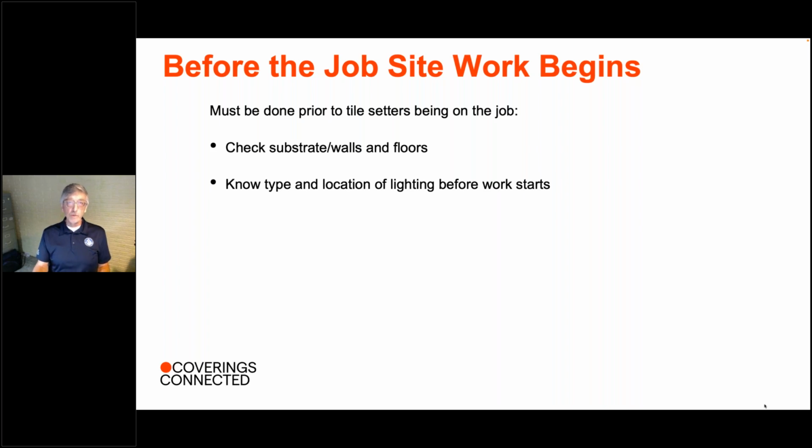Take a look at the window and door schedule, or maybe not the schedule, but the placement of the windows and doors, and see if there's a lot of glass that will be allowing natural light to shine in and enhance the beauty of your tile, or cause shadows along and across the grout joints and between the tiles on your finished installation. Important things that you want to know before the work begins.